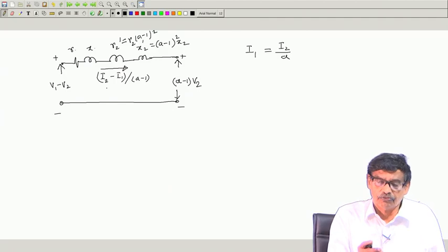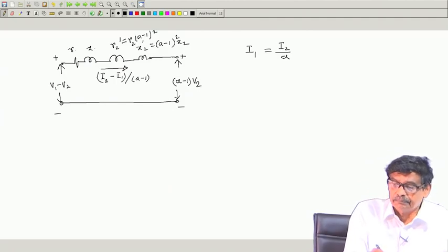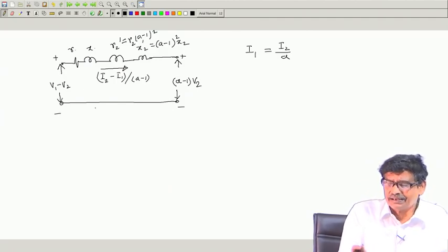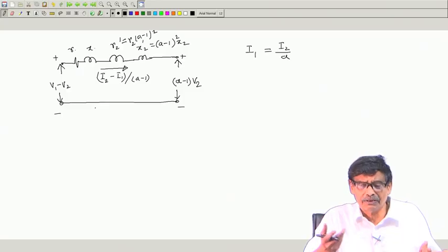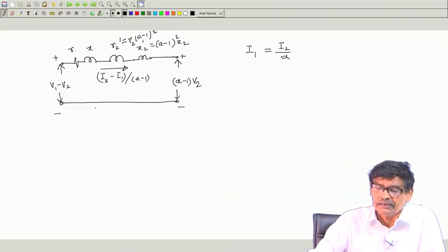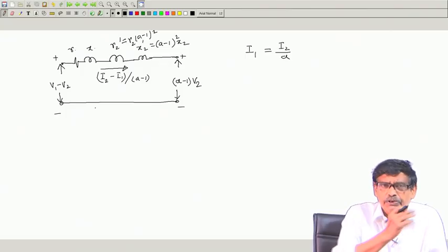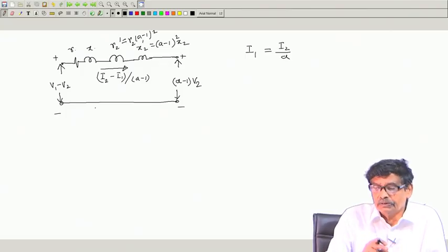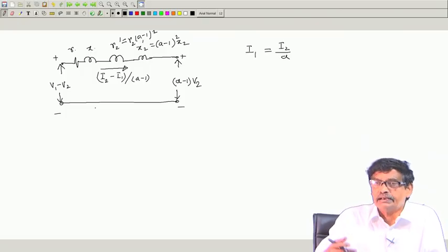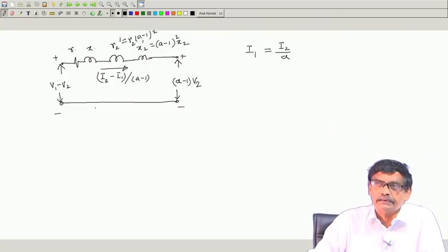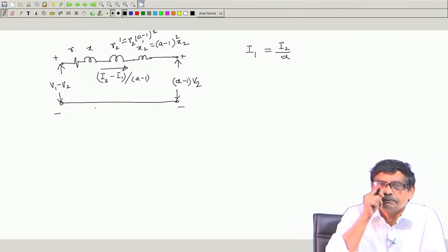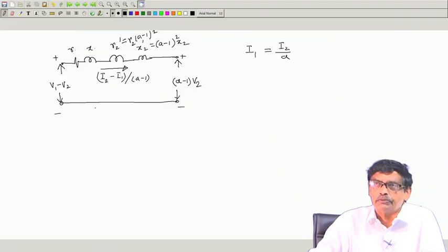Goal is to replace this with an equivalent circuit similar to that of the equivalent circuit of a 2 winding transformer. That is, my input voltage V 1 should be present here alone, load side there should be V 2 alone present, current some I 2 dash sort of thing should be present, things like that we are trying to do.